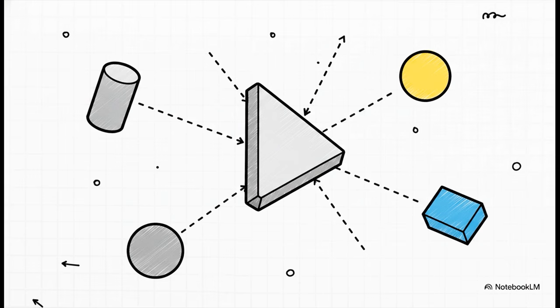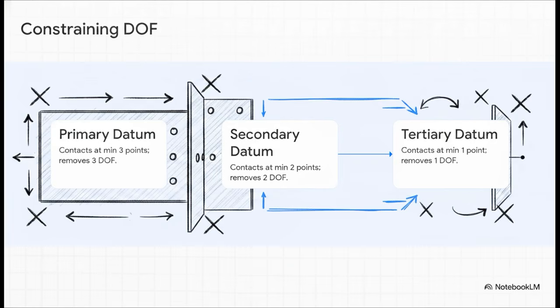Now, remember, according to the ASME Y14.5 standard, datums are theoretically exact points, axes, or planes derived from the true geometric counterparts of our specified datum features. So they're perfect in theory, and they are exactly what ties this messy, physical, real-world part back to the pure mathematical design intent. Okay, so how do these datums actually work together to anchor our part? Let's walk through it step by step.